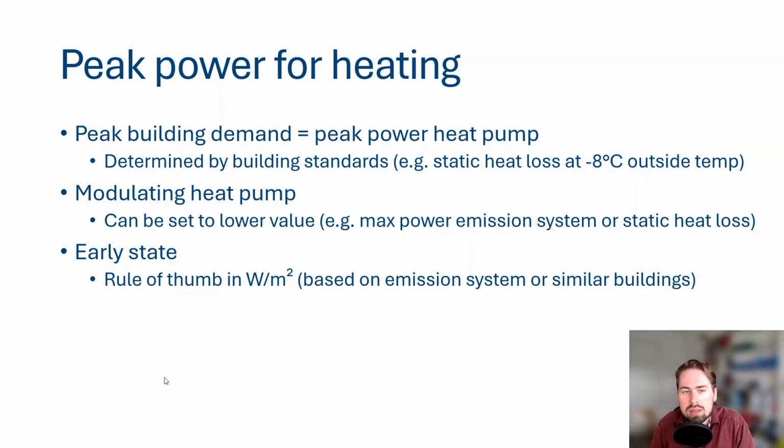And the last thing about this peak power is also the simultaneity. Now, we discussed it already quite extensively in a previous article, which is also linked in the description. But what we said there is that if we have, for example, 100 buildings or apartments connected to the same bore field, your peak power for your collective bore field is not simply the sum of all your buildings, because they do not occur at the same time. But that was covered last time.